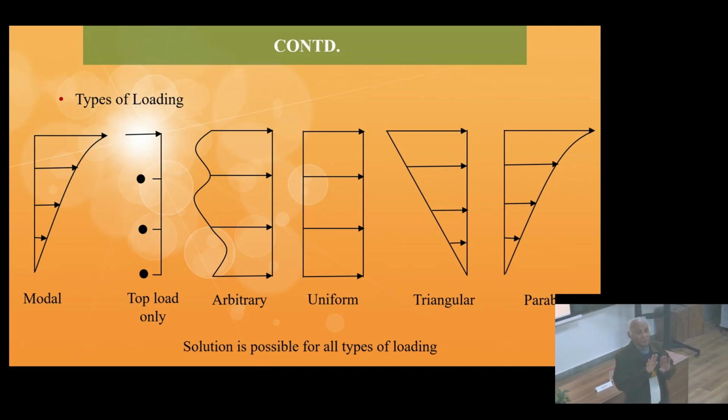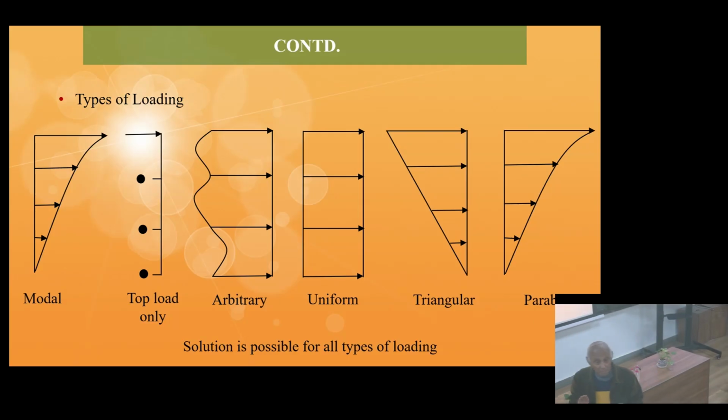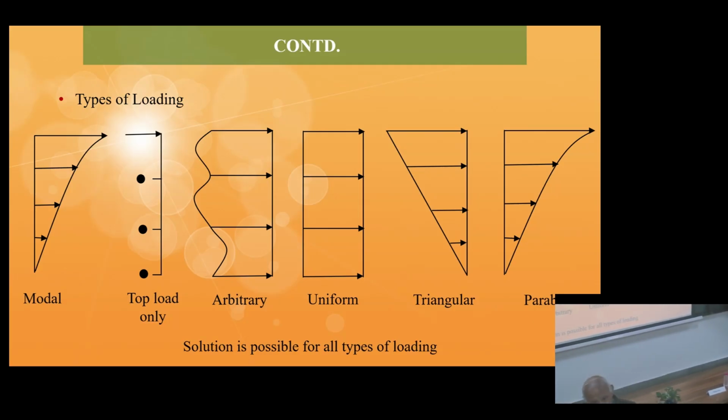So this is the force-based pushover analysis. Force-based pushover analysis means I can apply different types of forces, and these forces I apply incrementally. That means in steps: delta P1, delta P2, delta P3, delta P4. That way I can go on adding and increase the load. So this is what we call the force-based pushover analysis. Okay.